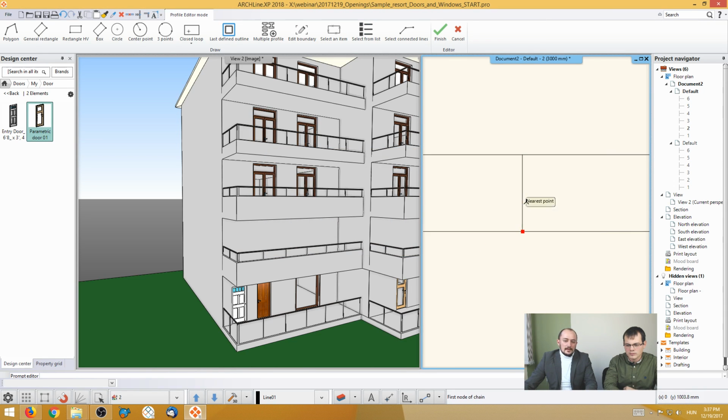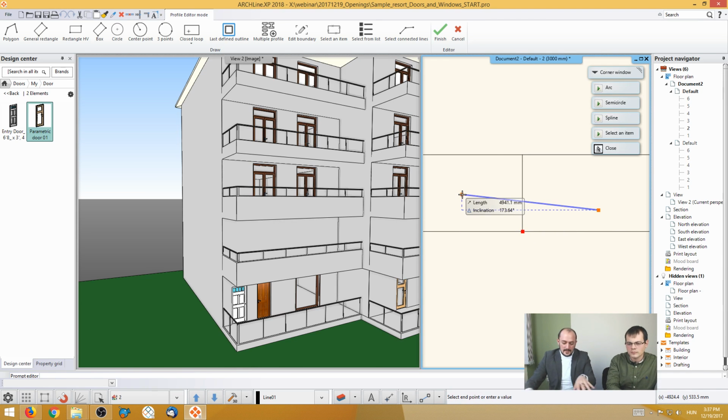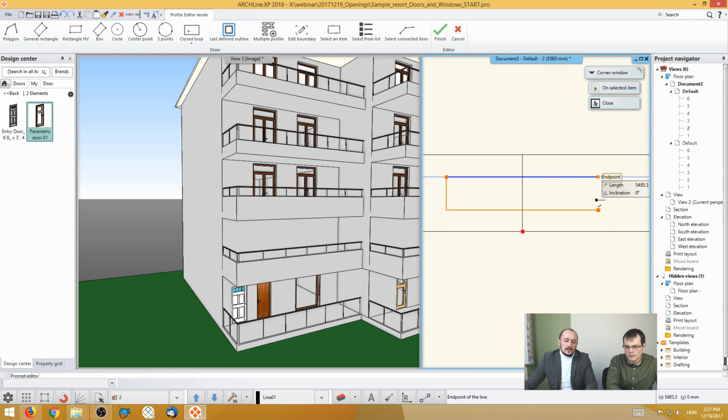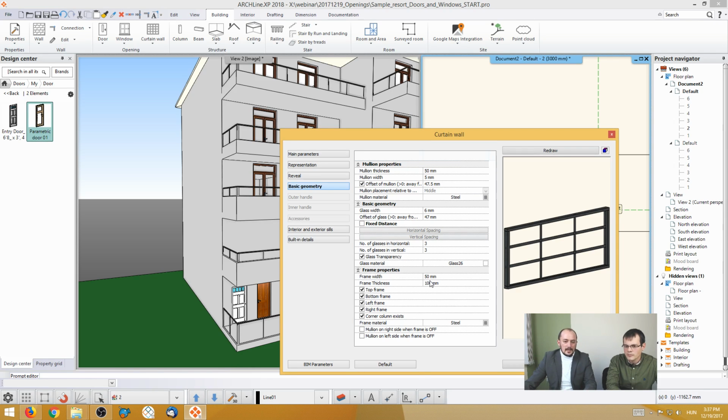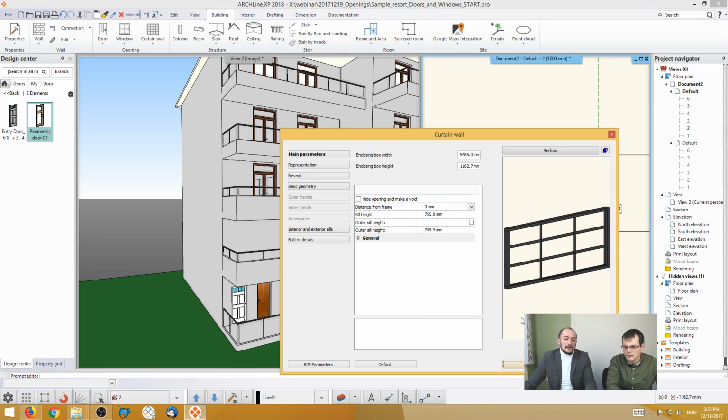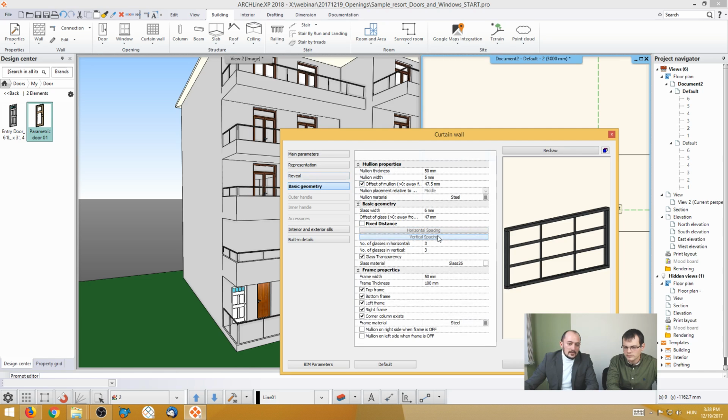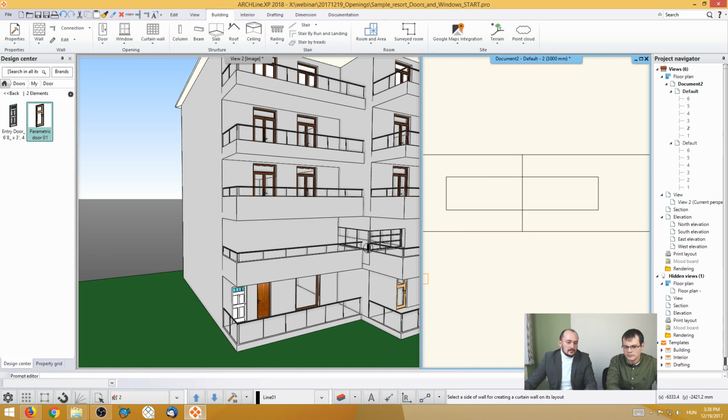Okay, and then I can draw also with existing values. I can type those. I can draw a shape, which then, when it's closed, I can set up panel by panel, set up the first panel, divisions, number of divisions, materials and everything else, also the mullions and then also the positions and the cross sections and everything like that. And when I've done that, I can do the same thing on the other side. Now let me just make a little change here to change the divisions to something else so we can see how they differ in the 3D. So this is what I've got here.